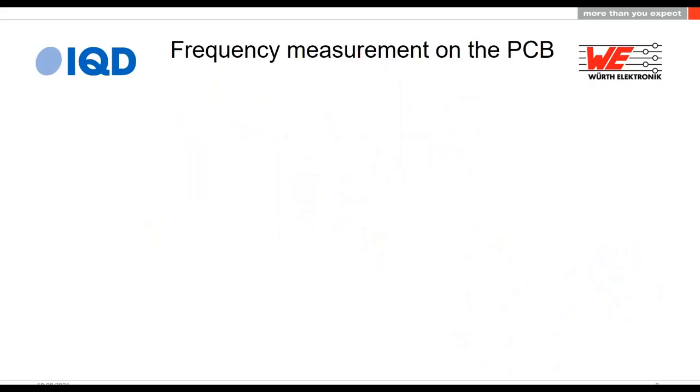The first measurement we're going to make is we're going to measure the frequency on the PCB. Yeah. Pretty obvious why we need to do that. The component that we're discussing is a crystal. It's designed to make a frequency. It runs on your PCB, so we better find out how it's running. We better measure that frequency when it's on the PCB.